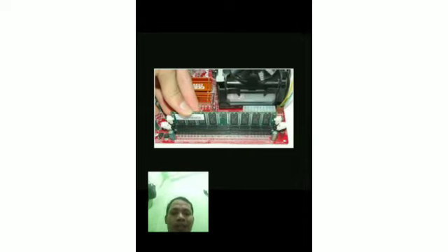4. Install memory. Generally, the memory used at this time is of the RAM type DDR2 and DDR3. So, make sure beforehand that the memory socket on your mainboard is a type that matches. Installing memory is quite easy, namely by aligning the notch in the memory with the slot on the mainboard.